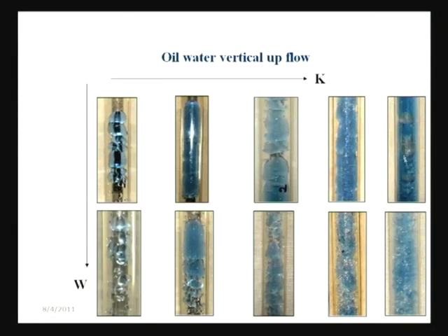There are some circular, large water droplets. Here we have brought out the phase inversion very well. Here it is kerosene dispersed in water, here it is water dispersed in kerosene. Such a situation you will not get for air water or vapor water cases. Here also we have tried to do it at a higher water velocity. Here we find that the kerosene droplets are smaller, and in this case water is very finely dispersed in kerosene. It is sort of an emulsified flow. So this is something very special for liquid cases.